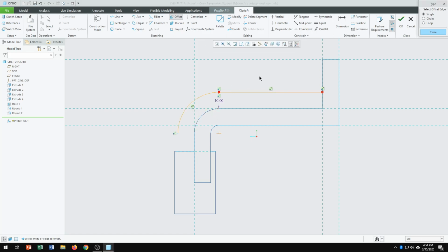Next, we're going to have a line connected from the end of that arc and coincident with this horizontal line. Then I'm just going to stretch the line horizontally, and then I'm going to trim. As soon as I use the trim, this line will be trimmed with respect to this reference line. See that? If I trim that, it trimmed all the way up to this intersection here.